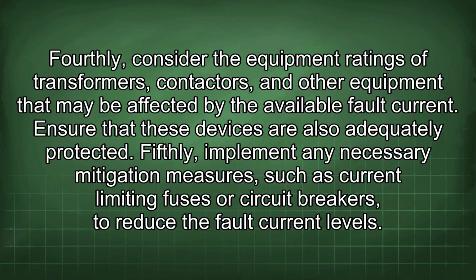Fourthly, consider the equipment ratings of transformers, contactors, and other equipment that may be affected by the available fault current. Ensure that these devices are also adequately protected. Fifthly, implement any necessary mitigation measures, such as current limiting fuses or circuit breakers to reduce the fault current levels.